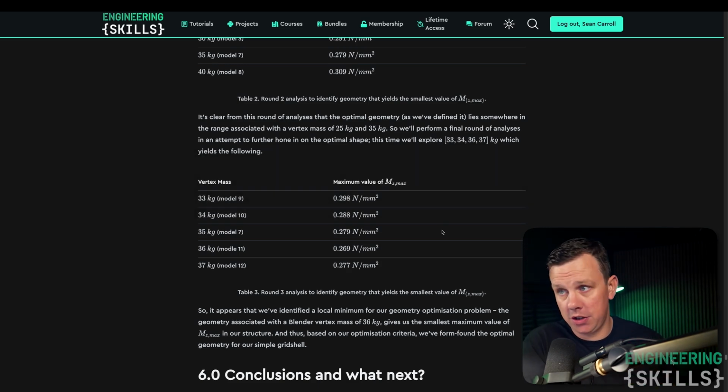Because this is part 2 in a series that looks at gridshell structures and form finding in particular. So this was an unstrained gridshell. What I really want to do, and what we're going to be doing in the next tutorial, is focusing on strained grid shells. Those grid shells that start out as a flat grid and are essentially pushed or bent up into position. And of course, that process of bending them up into position or lifting them into position induces stresses within the structure. And we want to be able to capture those stresses. And of course, those stresses are directly related to the shape that that structure will take. So that's going to be a really fascinating problem, I suppose, to get ourselves stuck into.